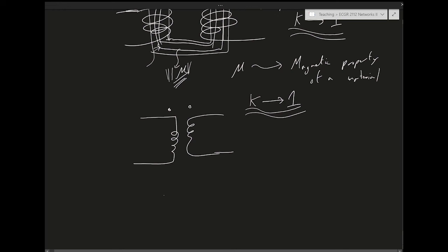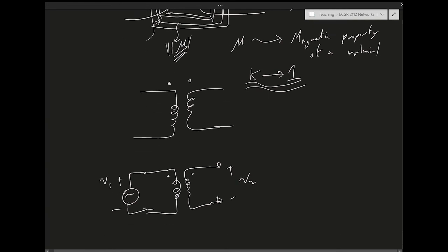The other thing is that for an ideal transformer to be desirable, another important property is that if one side of the transformer is open, let's say V2 is open, and we have a connection to the grid or some power supply on the other side, we want the current flowing. I2 is 0, definitely, because it's open. But we want I1 to approach 0 too. We don't want the transformer, if it's not connected on both sides, to draw a lot of current, right?